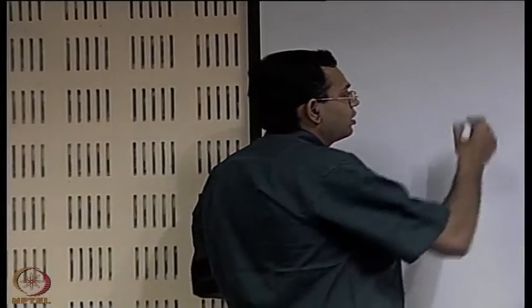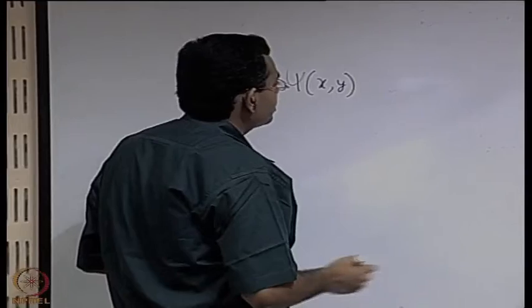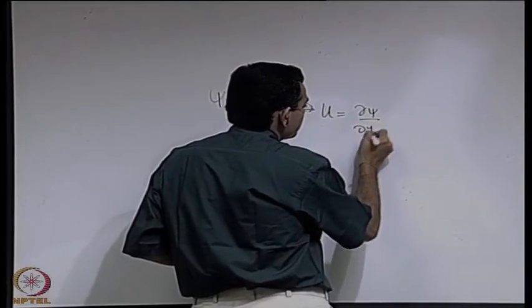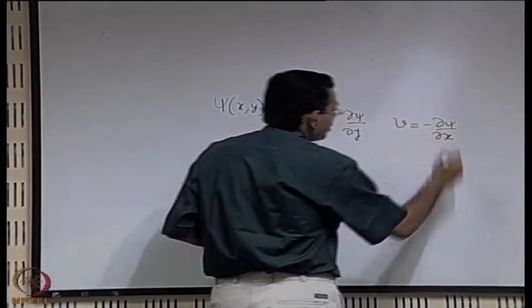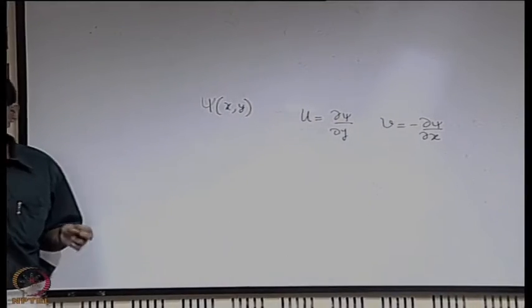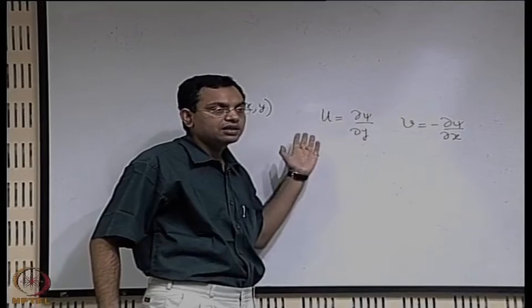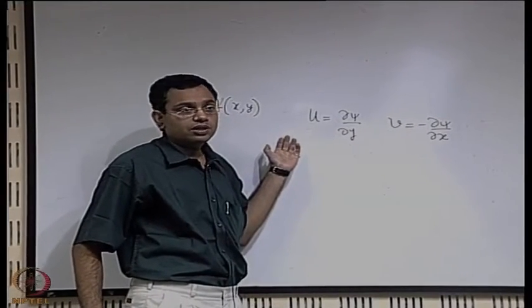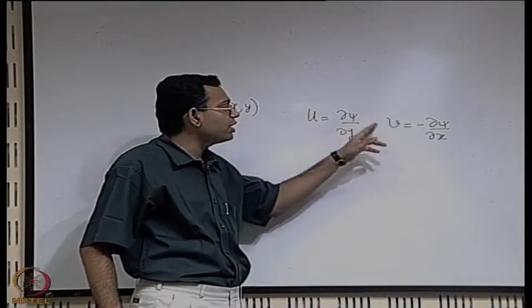Continue with our discussion on stream function. So, the stream function we defined as a function of x and y with an understanding that it should satisfy the requirement of mass conservation constrained by the continuity equation, and special case is giving that parametric form, two dimensional incompressible flow. So, the important thing to keep in mind is that it is defined for two dimensional incompressible flow in the way in which we are defining it.